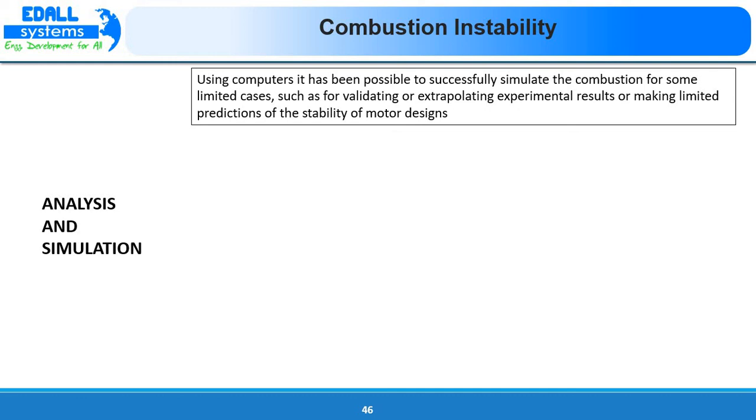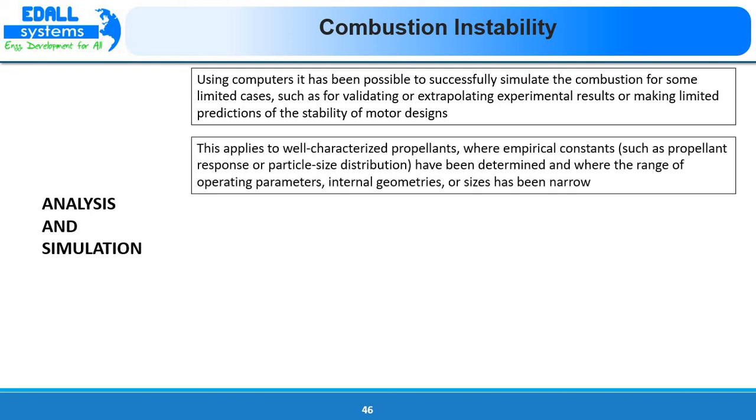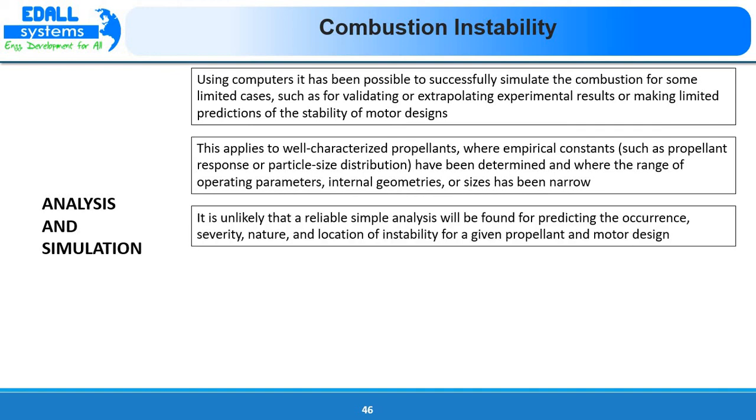So using computers, it has been possible to successfully simulate the combustion for some limited cases, such as for validating or extrapolating experimental results or making limited predictions of the stability of motor designs. This applies to well-characterized propellants where empirical constants such as propellant response or particle size distribution have been determined and where the range of operating parameters, internal geometries, or sizes has been narrowed. Then it is likely that a reliable, simple analysis will be found for predicting the occurrence, severity, nature, and location of instability for a given propellant and motor design.